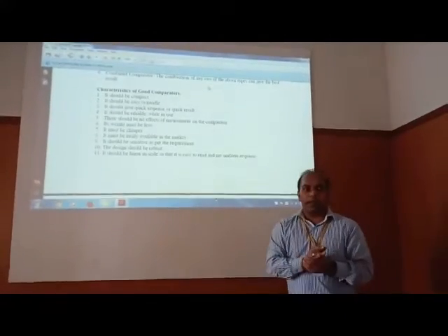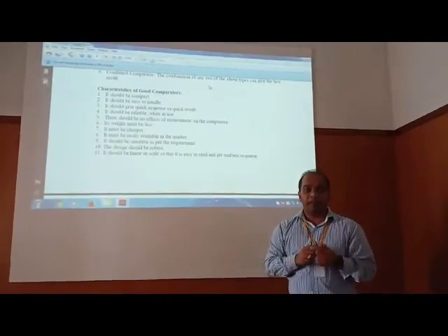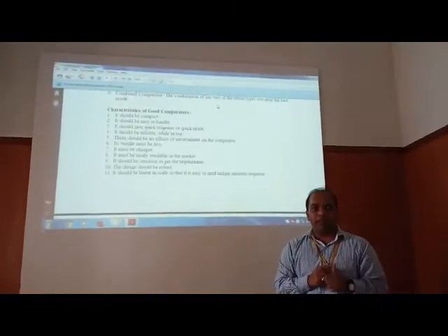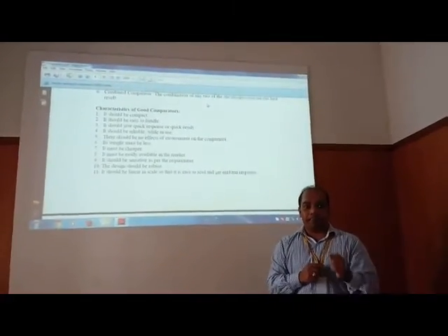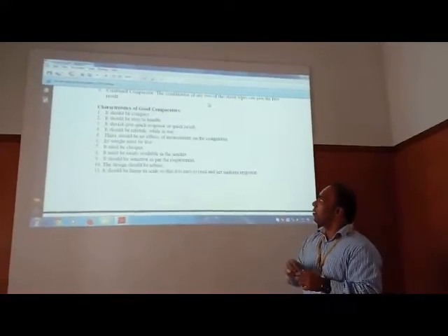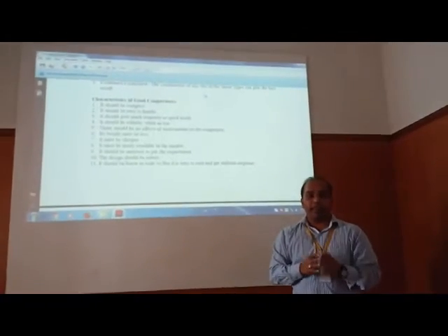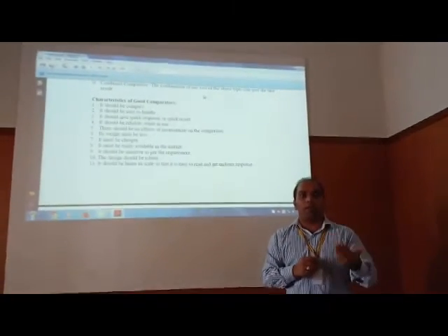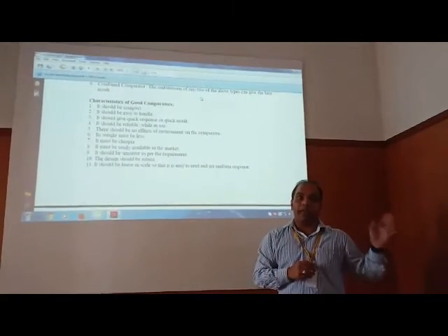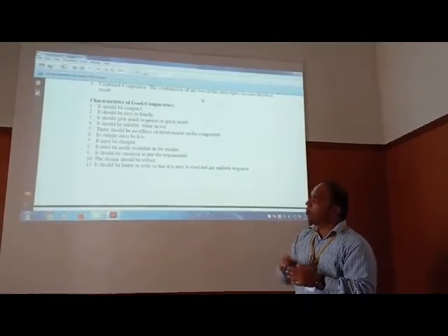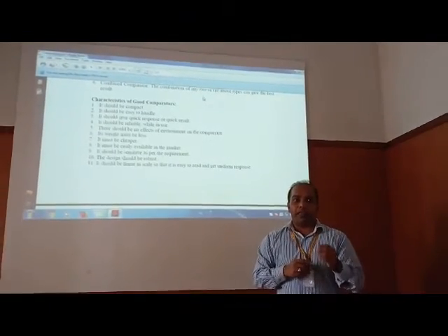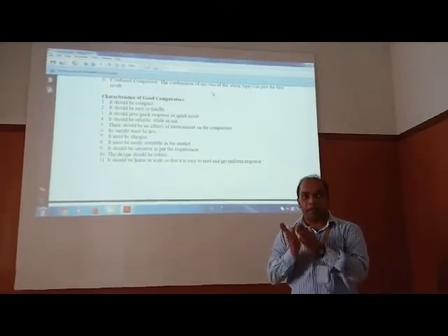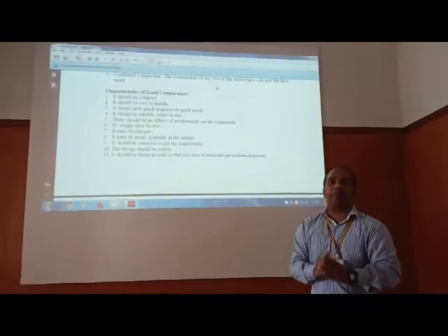It should be easy to handle. Now, this ease of handling is required in two terms: first is use of skilled labor and second is use of semi-skilled labor. It should give quick response or quick result. Since it is going to be used in the quality section, faster results will help to check more number of components. Therefore, it will help the production system. It should be reliable while in use. Since a comparator is going to compare an unknown quantity with a standard, we are totally dependent on the reliability of the comparator. Therefore, it should be maximum reliable.